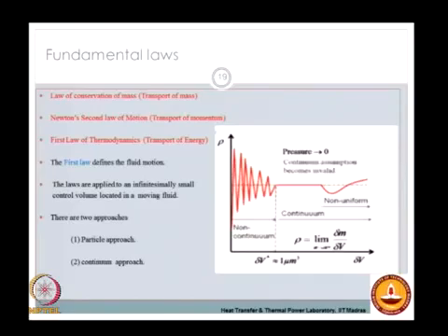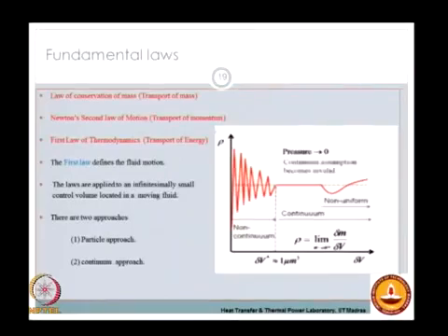We define a control volume in a moving fluid, and how we define continuum here is that you plot the ratio of mass by volume, that is density, for different control volume sizes, different delta V. Below a certain volume, approximately about 1 micron cube, the plot of density looks very distorted, with a lot of fluctuations.